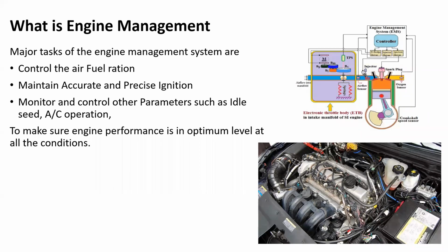But once you start the vehicle in the early morning, the engine is operating at a higher RPM, like 1200, 1300 RPM. The reason for that is to bring the engine up to the optimum operating temperature as soon as possible.